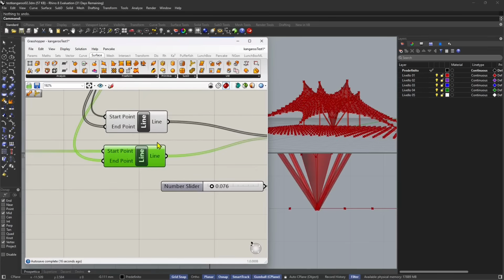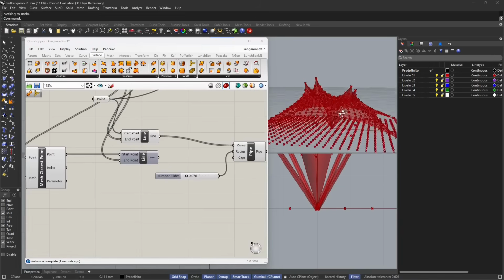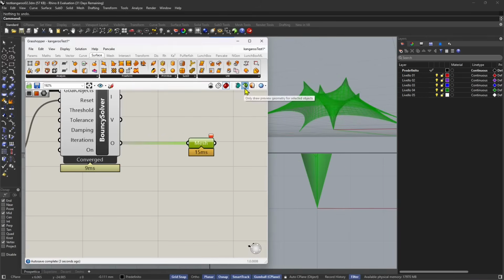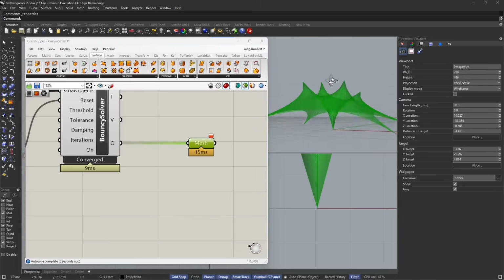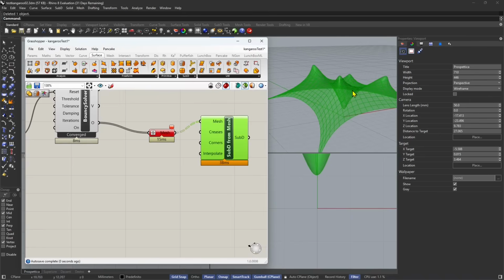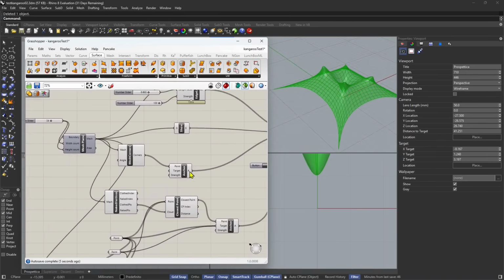Okay, so I'm going to hide now some lines. Actually, I want to use only those ones. I like this solution better. So we are outputting a mesh from this, which is giving us kind of an issue, but well, it's working. So this is the final mesh. So we can now bake this, or we can also smooth more. If you use sub-D from mesh, we can make it even smoother. But I don't know. It's up to you what you want to use.